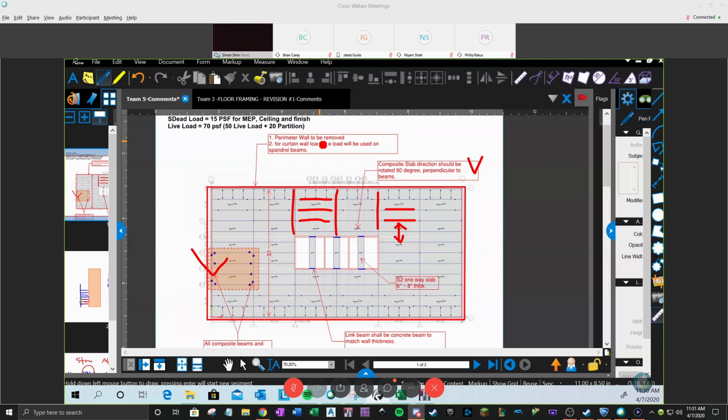Obviously, since this is a structural element, we treat it using cast-in-place concrete with all the reinforcement. Even though this works like an enclosure, this is a structural element. So sometimes it depends, but we should practice more, ask, and think about the structural system carefully. So here, the perimeter wall we treat as a glazing wall.